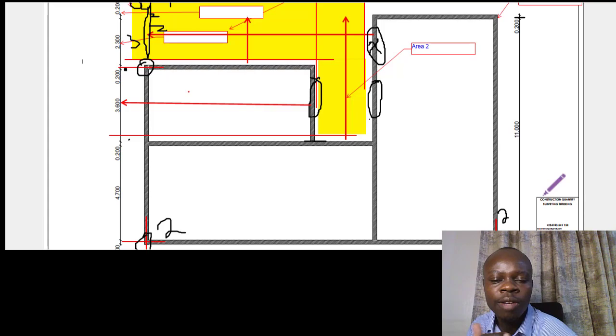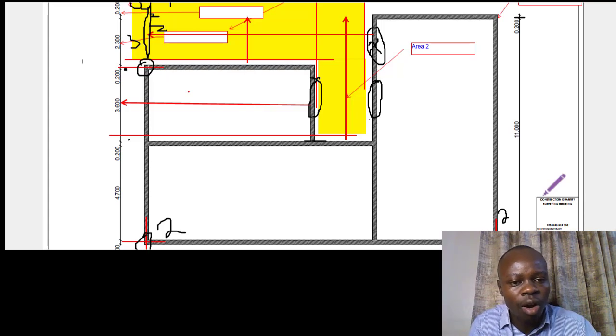So without even more explanations here and there, you hear that we are going to take that given thickness of the wall, the full of it, times 4 corners. So despite the number of corners that you have, the rule of distance moved, which is now taking that particular thickness of that particular wall and multiplying by 4 corners, still gives you the correct answer.